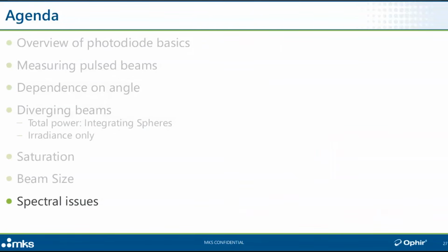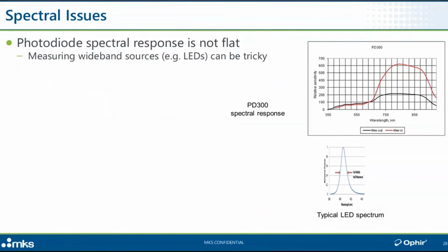And last item, spectral issues. Okay, anyone who's at all familiar with semiconductors and optics and where the two of them meet will know that the spectral response of a semiconductor photodiode is not flat. It goes into the quantum mechanical nature of the energy levels of the atoms in the material and the physical mechanism by which photons of light are getting absorbed.